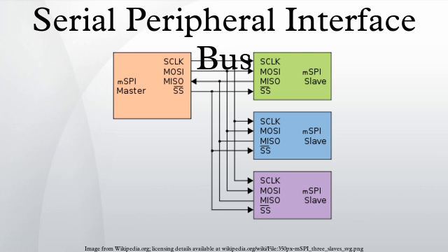Multi-IO SPI: as opposed to 3-wire serial buses, multi-IO SPI uses multiple parallel data lines to increase throughput. Dual I/O SPI using 2 data lines has comparable throughput to fast single I/O. Quad I/O SPI using 4 data lines has approximately double the throughput. Multi-IO SPI devices tend to be half-duplex similar to 3-wire devices to avoid adding too many pins. These serial memory devices combine the advantage of more speed with reduced pin counts compared to parallel memory.